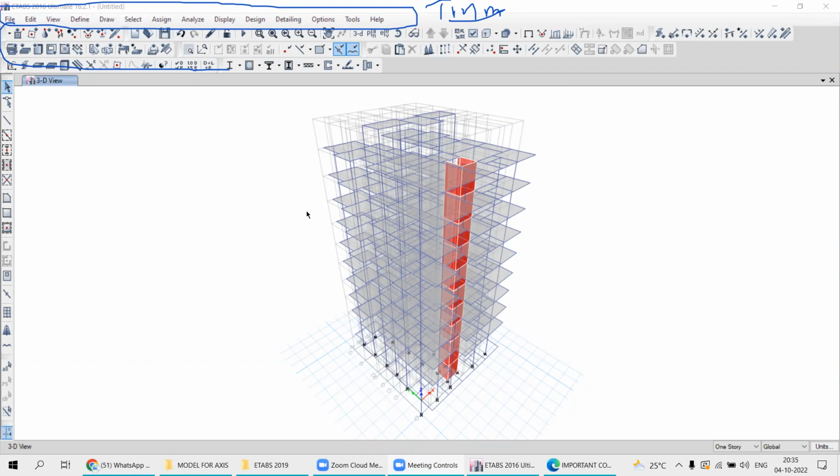the experience of using CAD software. So in CAD software, we have the shortcut keys: L enter for line, C enter for circle. A trim command is there, TR enter, and offset is there. So those are the shortcuts. In ETABS software, some shortcuts are there, but consultants are not using the shortcuts in ETABS software, and it is not needed. Why? Because we have these shortcut keys here that we call the quick access bar.